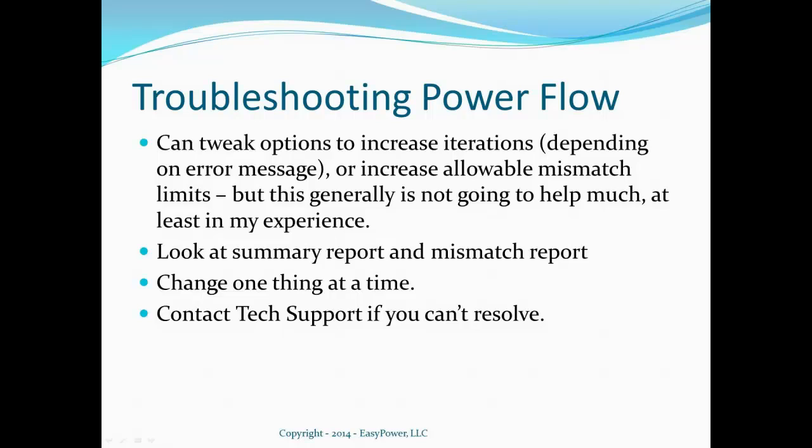That's really only going to be the case for extremely lightly loaded motors because you can reduce the reactive power. But if a motor needs to put out 10 kW, it's going to have to put out 10 kW, and that power has to come from somewhere. So reducing the voltage is not going to change that. So it's a very limited capability, and that only really works for very lightly loaded motors.